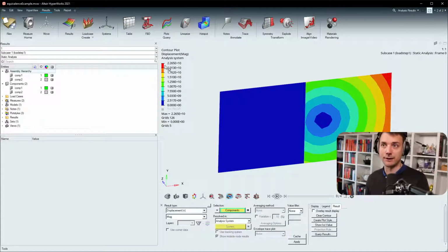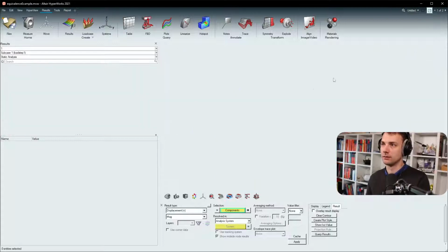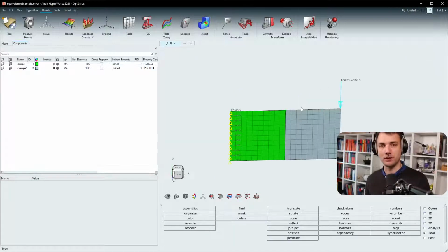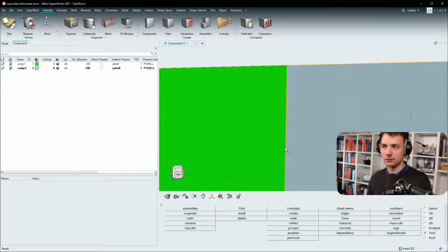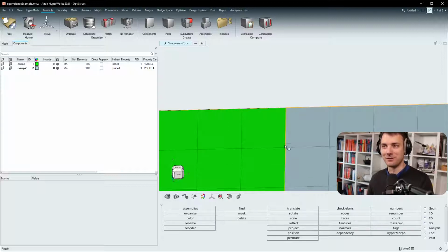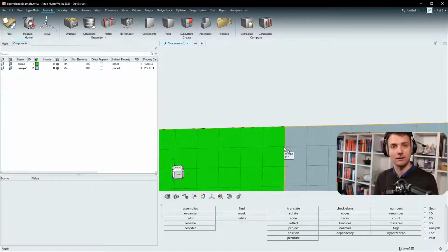So you have large displacements, and that comes from a pretty bad setup here, because you think those are one node here, one node. So every node is one node, but there actually are two nodes, because the lines did not know each other, and the mesher just put the nodes on the same locations, but there are actually two nodes. And those two nodes don't know each other, so they don't transmit force, so it flies away.